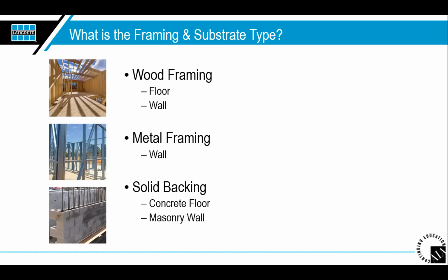install tile on it? Well, we are going down a whole other road now of, for interior applications, for example, you can actually use moisture mitigation products that would actually allow you to get on the product just as fast as you could walk on it, basically. But like I said, we still have the exterior applications that are happening where moisture mitigation testing needs to be done, and that may need to be a part of the specification as well.